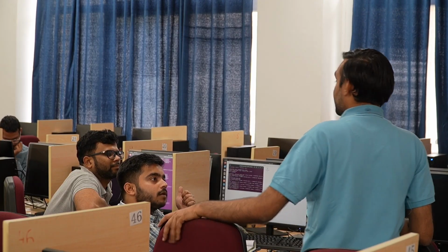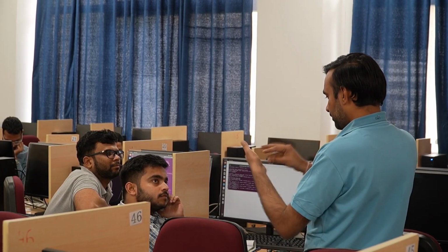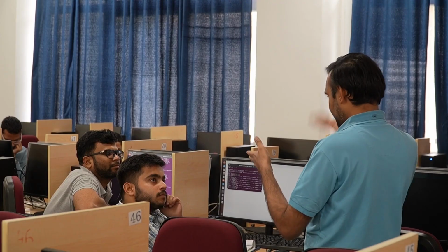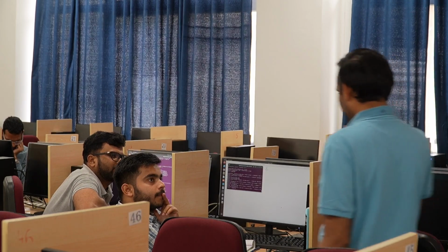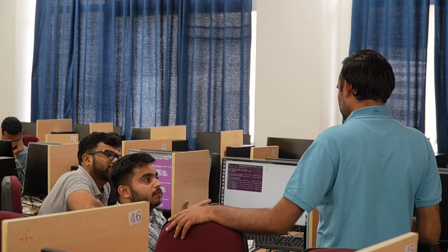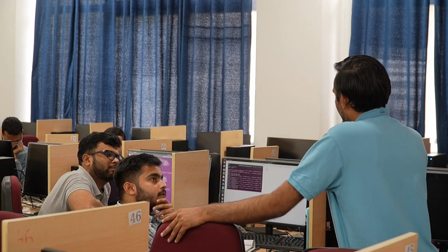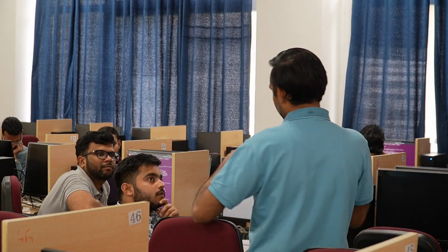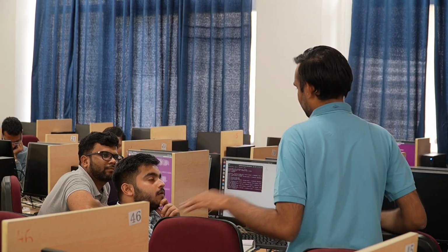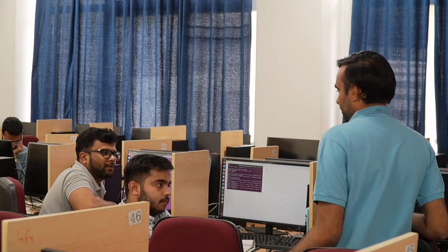Source code means the SRC folder. In SRC you have to find the portion of the code where the command that writes output is written. In that command you have to do a modification. Instead of calling all the variables, you may remove the pressure variable from there, then it will not be written. Yes, because at every write interval it will be saving, so it can take more space and time. That is the reason whenever we do simulations, it is not recommended that we save data at every time step. We save data after a good number of time steps.